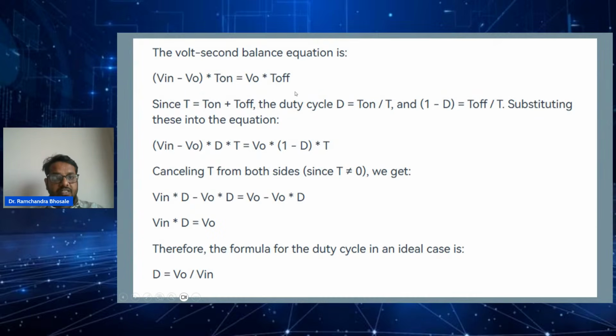This has to be equal if you don't want the inductor to saturate. The volt-time balance should be equal in the on state and off state, and only then will your inductor current not saturate.